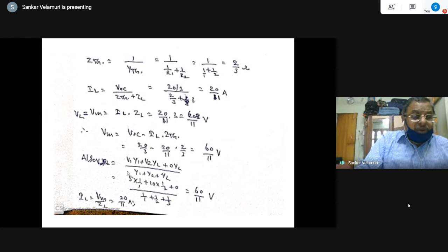Unbalanced voltages can be resolved into symmetrical components: zero sequence, positive sequence, and negative phase sequence voltages. Millman's voltage is equal to the zero sequence voltage that can be computed sometimes. So all these things are similar, but that is the application aspect of it. I am only representing the statement of the theorem from the electrical circuit point of view for this particular subject. But having got the exposure in these things, I thought I can share my views, so as not to get confused in this.